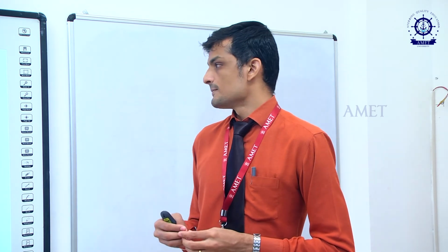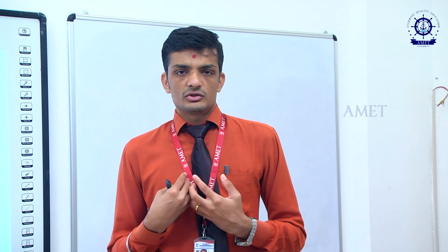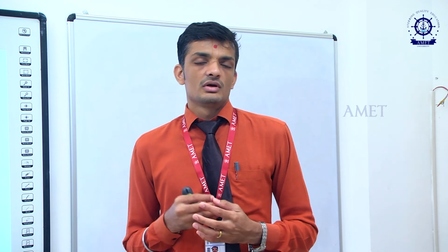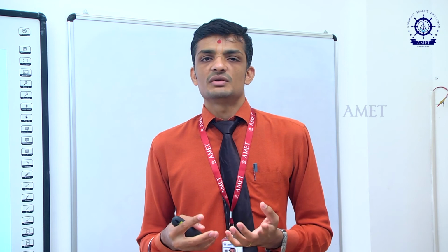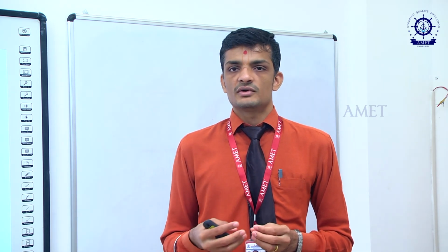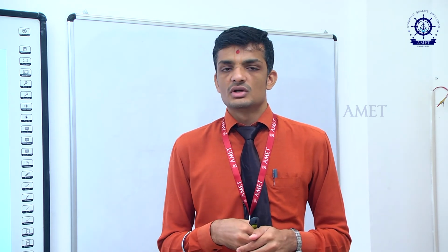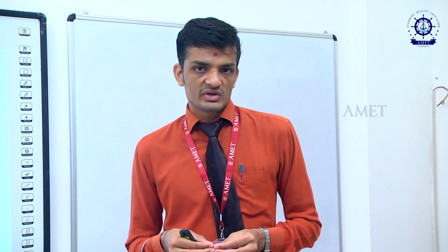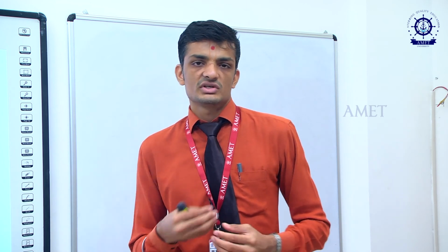In FEA it remains the same, and you got to select your shape function. So what is the shape function? In a structural problem, my prime requirement is displacement. Since I have already discretized the domain, I would like to know how my displacement is going to behave within the element. Is it going to be a linear behavior or a non-linear behavior? Based on that, I will choose my function which represents my displacement. That function we call an approximating function. Later you convert it in terms of the element, and it gives something called shape functions. So it is a whole process.